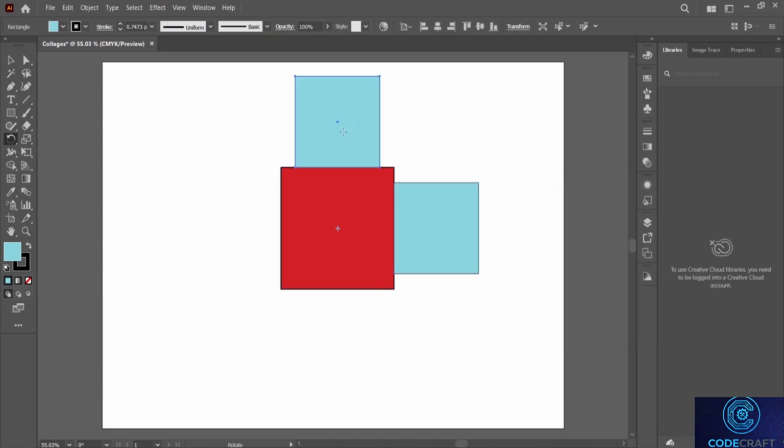And afterwards, you'll see that there's a new rectangle over here. Let's just press Ctrl D afterwards to copy it in all directions. Okay, now that we're done, let's go ahead and show you how to make a different type of design over here. Since I already created this, I will just press Ctrl Z to undo all of them.